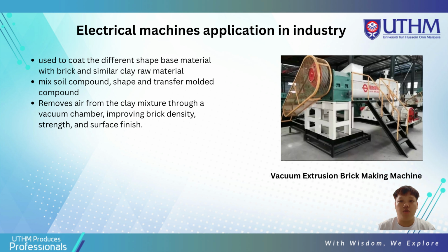So this is the table for the machine. The production capacity is around 12k to 13k, and the spindle speed is 32 RPM. The total power is approximately 160 kilowatts, and the total weight is around 11k kg.